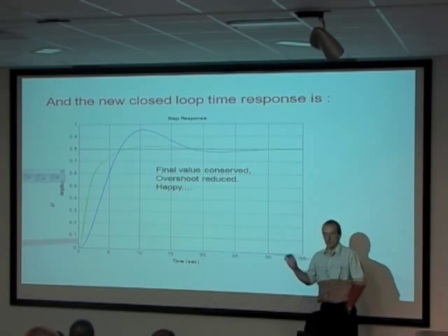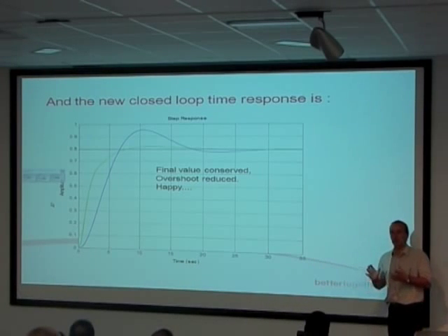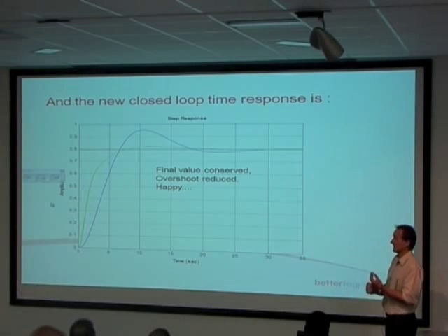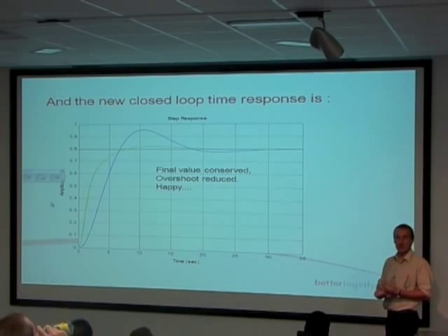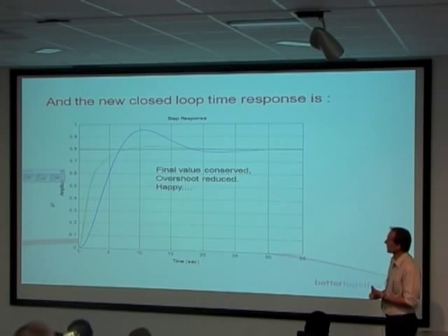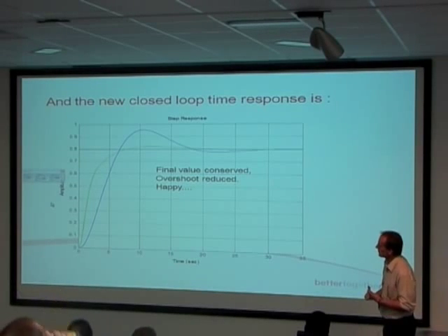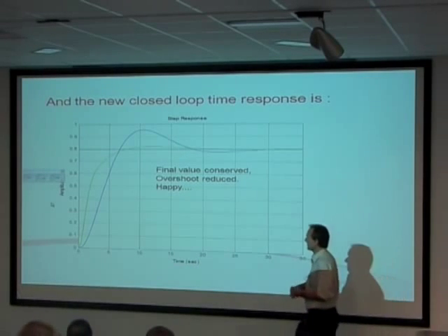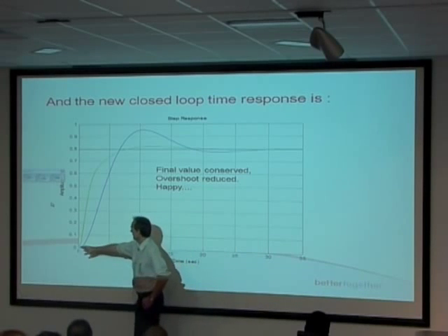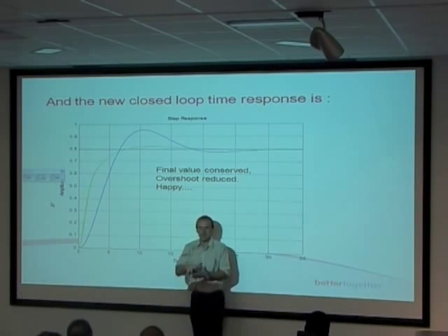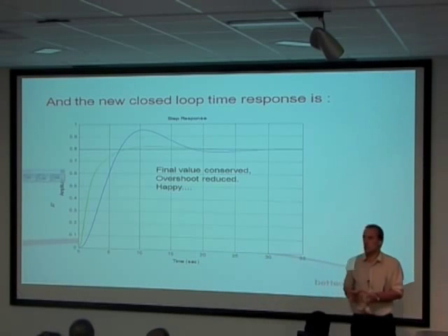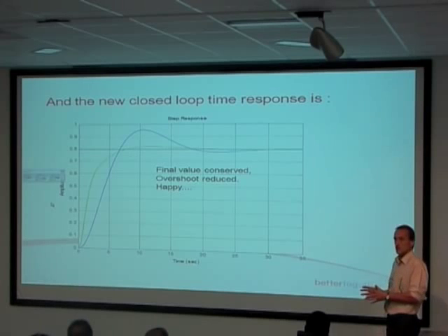So if you look at those responses and think of the terminology from when we were talking about time responses, thinking about things like rise time, settling time. The rise time, to be fair, isn't very much changed, because the rise time really is about this first bit, isn't it? Between 0 here and 0.8. That's the bit where we're concerned with the rise time. So that definition, I haven't managed to change very much. The settling time, I would argue, is massively improved.